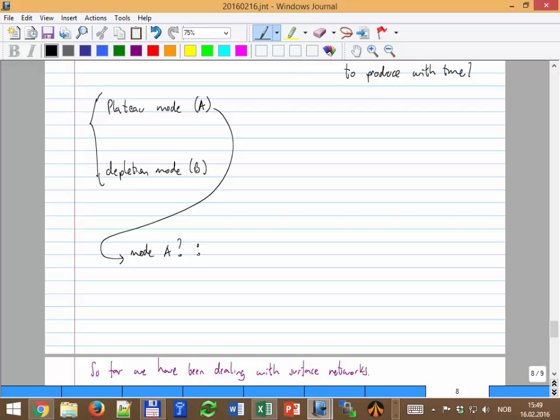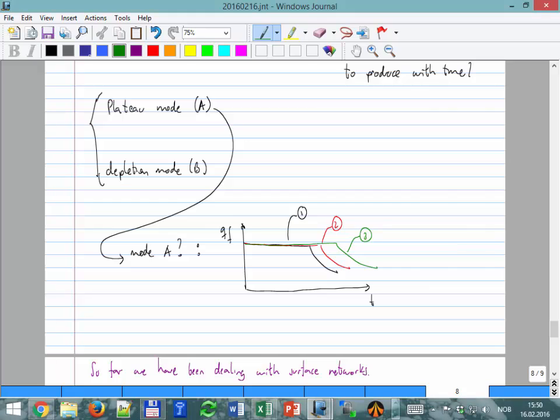The ideal, from the reservoir simulator perspective, is this: I have the Q of the field versus time, and then I have a plateau and a decline. That is option 1, for example producing with a certain ratio. Now I try another, and I get this number 2, then I try another one. These are with different well offtake. Of course here the decision is obvious. We are going to choose the alternative that gives us the longest plateau.